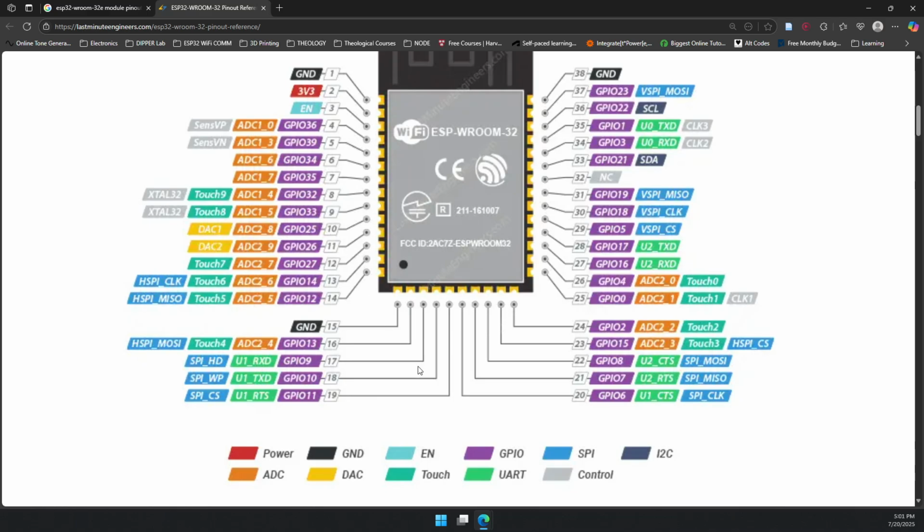You see, the thing is that in the ESP32 pins, a lot of the pins are multi-purpose, meaning that GPIO 36 can act as a GPIO where you just apply ones or zeros, or read ones or zeros, or you read analog values. Okay. Over here, 35 is a GPIO, but it can be used for serial communication. And then we have touch pins, we have SPI, we have pins dedicated for SPI. SPI is also a communication protocol like UART. Okay, so that is why we have multiple tags over here. So the ADC pins are the orange ones. So which one should we use? So a piece of advice over here.